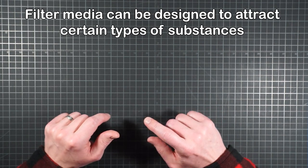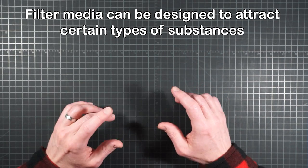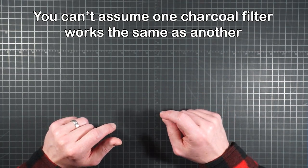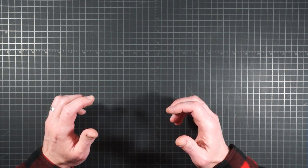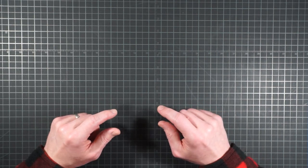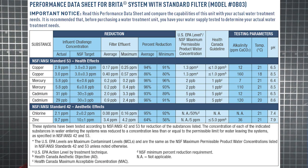You see, based on the way adsorption works, filter media can be, for lack of a better word, tuned to attract certain substances over others by the materials and additives used. So as such, you should never assume that all charcoal filters reduce a similar list of substances. The selection of treated impurities can be a seemingly random mix. So in choosing between filters, you might literally have to opt for lead reduction instead of copper, for instance, or vice versa. So to illustrate the point, here's a look again at Brita's standard filter datasheet.